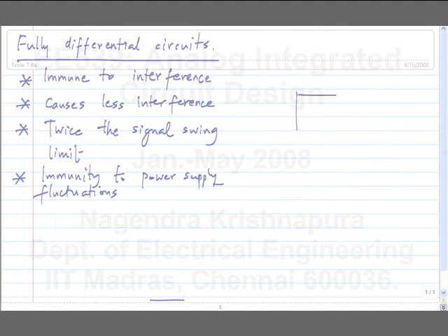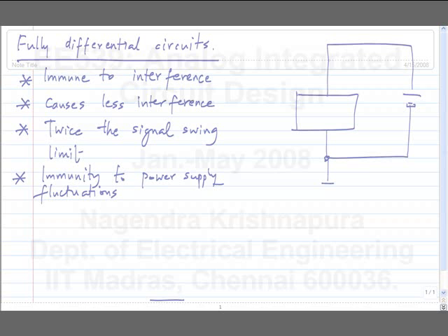If we have some circuit and it's supposed to be supplied by an ideal voltage source, but it's never supplied by an ideal voltage source, this will have some impedance which includes resistive and inductive parts. The current drawn through the power supply can change with time. So which means that although this voltage is fixed, the voltage across these 2 points will have some fluctuations.